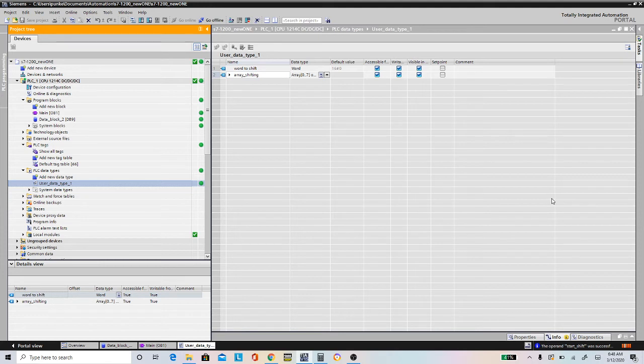For some reason, Siemens internal memory does not really register itself as a word. Like let's say MW0, right? You would think it'll let you use 8 bits in that MW0, but for some reason those internal bits from Siemens do not really perform like an actual word. I think it's because you're not really supposed to use those M bits for stuff like that.